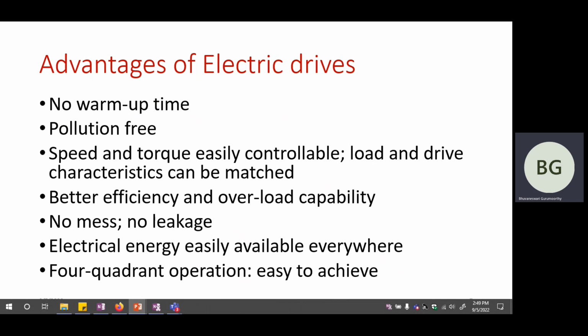advantages of electric drives? If a thermal power station is shut down for a few days, which is actually driven by steam, right? The turbines are driven by steam. So if you want to turn on or put into service a thermal power station from its off situation, it will require anywhere between 12 to 15 hours minimum, because you have to first make sure that the boiler is functional. The fuel is burning in the boiler.